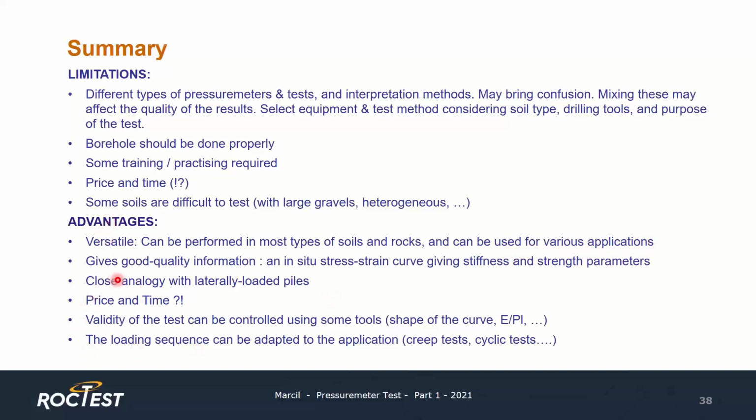A second advantage is that it gives very good quality information. It provides information on both the strength and stiffness of the soil. Also, there's a close analogy with the laterally loaded foundations. So that makes a very good test for these types of foundations.